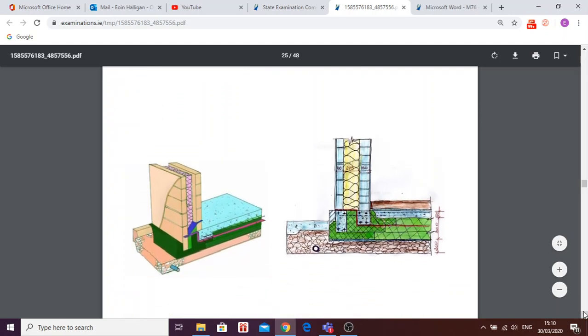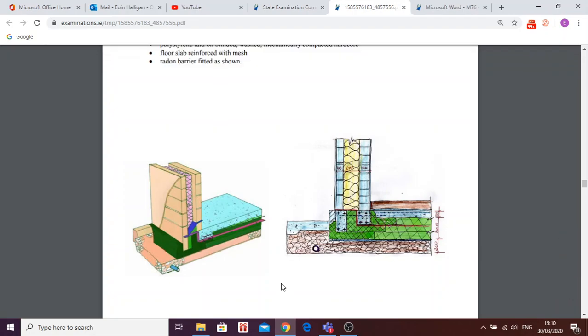Now, I'm not going to even look at the bullet points. I'm going to go down to these diagrams here. So these diagrams show me basically exactly what I need to know. These green sections here are made from expanded polystyrene, EPS, and they basically create a formwork. So you can see your hardcore down here, and in your green sections here, you have your EPS. So you buy those forms, they're L-shaped. That goes down on top of your blinding, and they create a formwork.